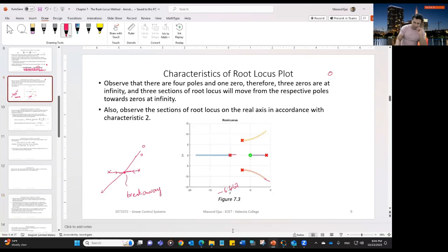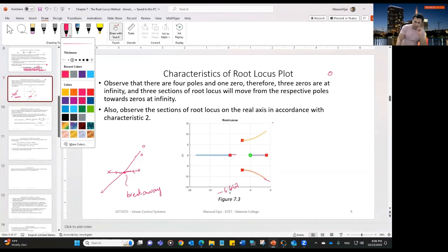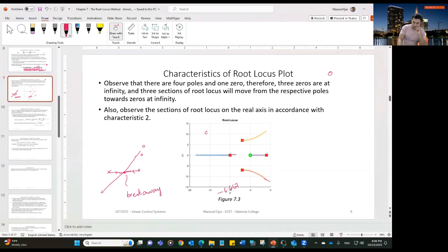That means if you have a pole, or a zero sitting over here somewhere, or let's say you have a pole over here or a zero over here, then from one of the poles, your curve is coming towards a zero. Then this angle with which it is coming with respect to the x-axis is called the angle of arrival.